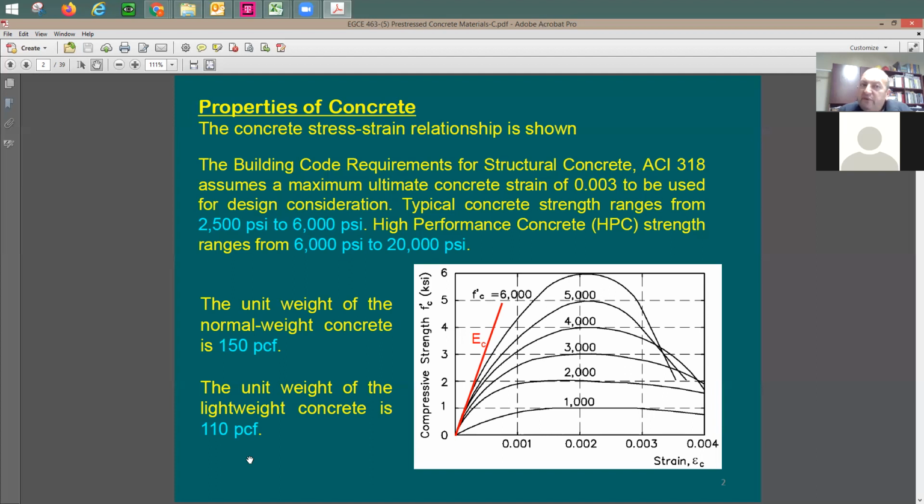So in a reinforced concrete, pre-stressed parking structure, you'd go with the double T's to be lightweight, and the columns most likely are going to be normal weight. So it is not necessarily that all the members can be made out of the same concrete in terms of normal weight or lightweight, but you can pick and choose. Beams, usually we do out of normal weight. Columns can be normal weight. Double T is the thing that takes a big volume. We try to make it as lightweight. And we understand the reason. Our target at the end is to have a lighter structure.